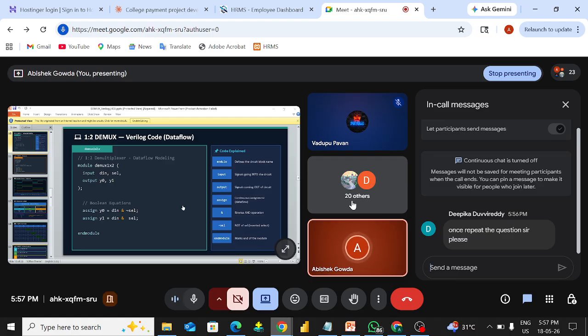If you find a bug or error after generating your design, think now you have generated a design for a demultiplexer, and you apply the RTL design flow. What is the first step? Specifications, right? Second is coding, RTL verification, simulation, and after that logical synthesis.